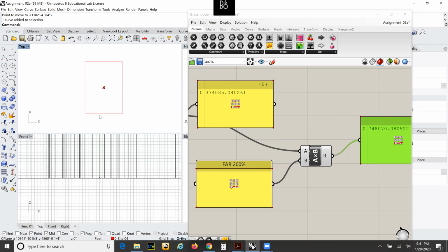However, the city is like, well, we're going to give you setbacks, and setbacks are really important because they give distance between the buildings. That's what generates the alleys. It's for maintenance, for utilities, for service. It's also important for the people experience because if you want restaurants with sidewalk dining, the setback is going to be set back from that property line. So we really can't build all the way to our property line.